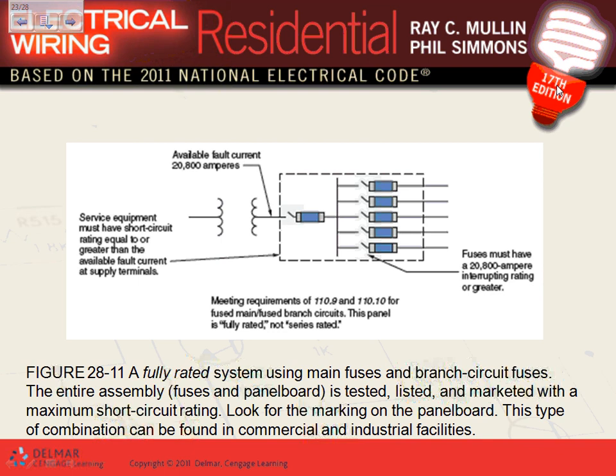And if you have, look at that. This is related to the short circuit. If you have a short circuit, look at the short circuit right in here. If I made a short circuit right here at the terminals of the transformers, three phase, I'm going to find this amount. This is 20.8 thousand amp that will be rushing right through my switch gear if I made a short circuit right at the transformer terminal.